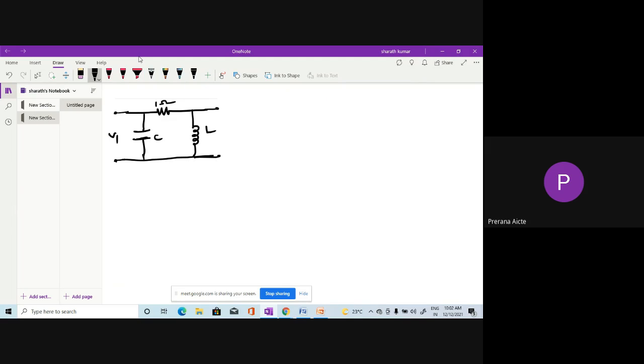So obviously V1 and I1 here. This is the simple circuit they gave, and you need to find Y21. Generally, Y parameters are called short circuit parameters or admittance parameters. The name itself gives this information. By short circuiting, we calculate the Y parameters. So the procedure to calculate these Y parameters is the short circuit method.